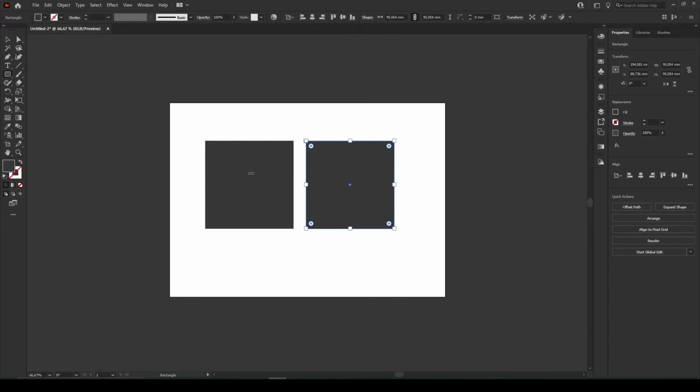We now have two rectangles in our field, and you can see from the control panel above that one rectangle is active, but I want to select another one, but the other tool is currently active. First, let's press the V key on the keyboard or select the selection tool from the toolbar. This tool is used to select objects.